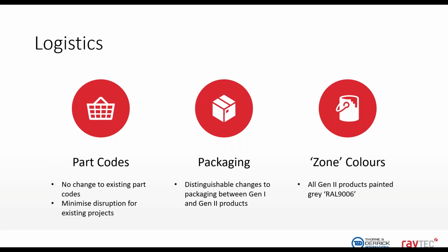So there's no differentiation any longer between Zone 1, Zone 2 and industrial product, but this has been done based on feedback from lots of our customers, and long term allowed us to provide the best possible lead times, and also has the added benefit of allowing certain spare parts such as PSUs to be used across different zone variants. So you don't have a dedicated Zone 1 spare part, you can use that across the Zone 2 variant or industrial, which gives you an added benefit if you've got different products and different certification requirements across the site.